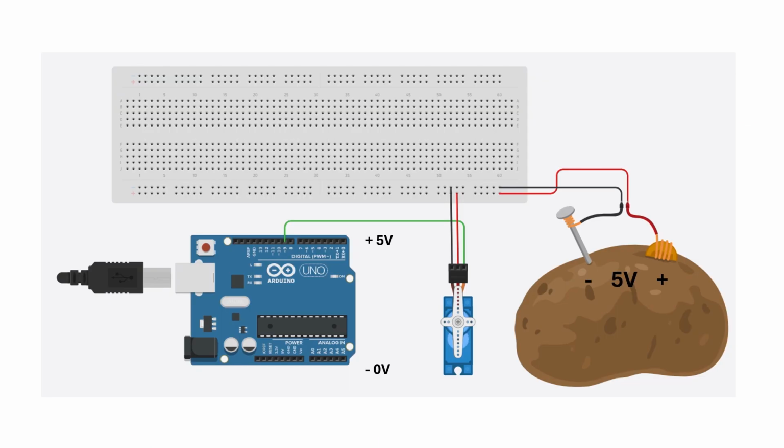So let's compare that to our circuit here, where I have an Arduino that is able to provide a 5-volt difference between its 5-volt pin and its ground pin, and I also have an external voltage source that can do the same. But if I were to call the ground pin of the Arduino 0 volts, that doesn't mean that the negative terminal of the external power source is at that level. It might mean that it is at 10 volts and 15 volts as its positive and negative respectively. Now, of course, this is going to create problems.